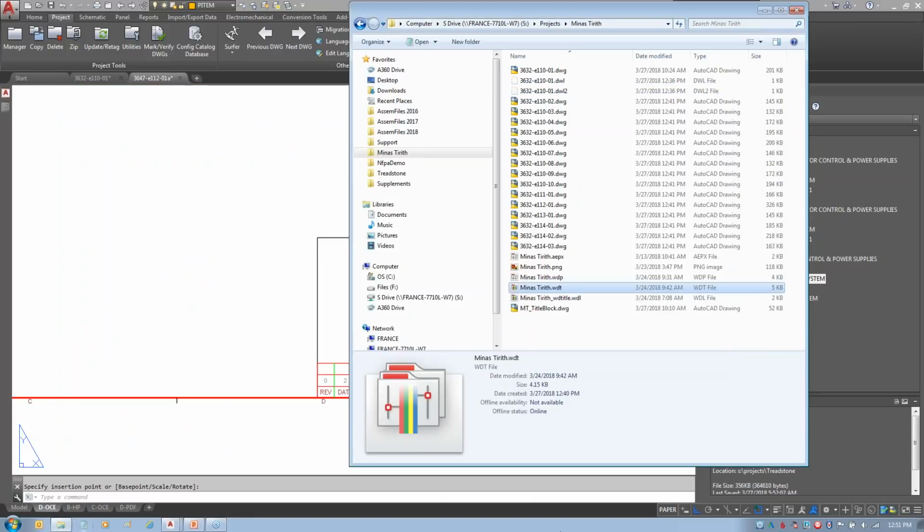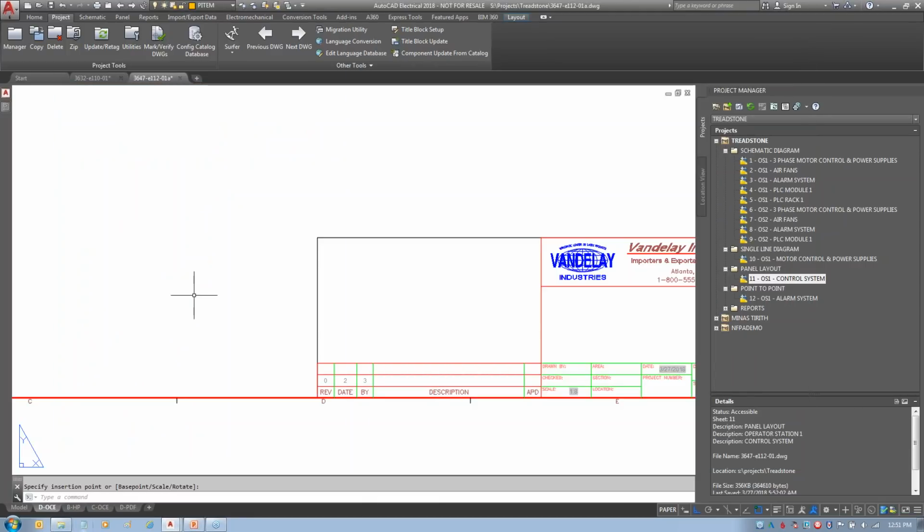Sure. In my experience, the one thing that I would definitely recommend as far as your attribute name definitions is don't use weird characters in those names. The main reason is that when you go to that WDT file, it has to put an accent marker in front of that character, and that in turn changes essentially the functional name. So in years past, we had like drawing pound for drawing number, and when you go to the WDT file, that name doesn't match the attribute name in the file itself. So, just take those goofy characters, wildcard characters out of the attribute names just to save yourself some headache there. Yeah, there's a lot of characters you can't even use in an attribute tag.